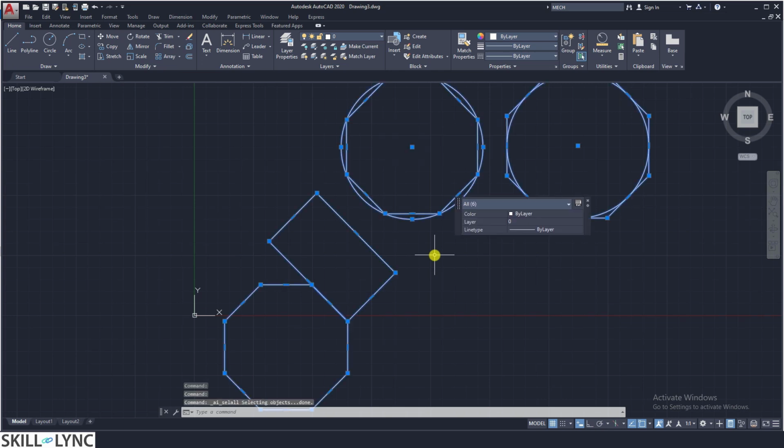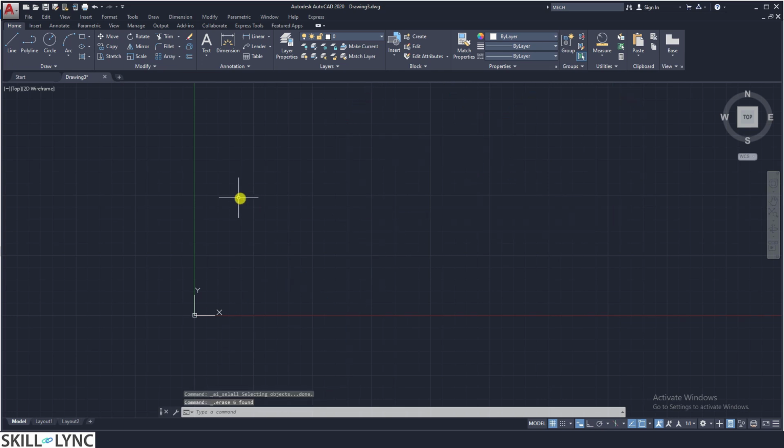So now let's look into the polyline method. Polyline is that you can draw a line as well as extend it to a polygonal arc or an ellipse based on the requirement. So it combines a line, a circle, an arc together. In order to simulate this, you can type in PLINE for polyline. It will start off as a line.